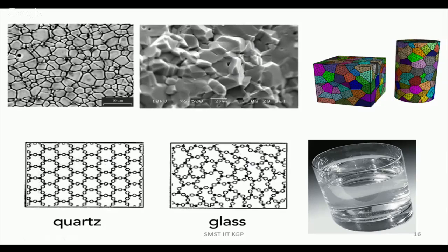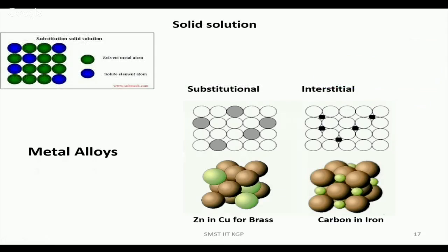And glass doesn't have any grain boundary, polycrystal has many grain boundaries, okay, and grain boundaries are also like a defect. I mean, it's not exactly a defect, but grain boundary is important, and also you cannot avoid the grain boundaries, and grain boundaries also sometimes help the crack to deflect in different directions. That is important. I will discuss it in the next class. I think I can stop here.